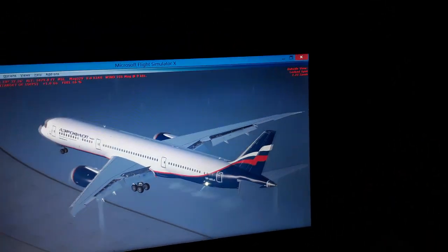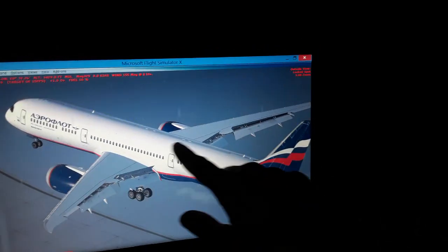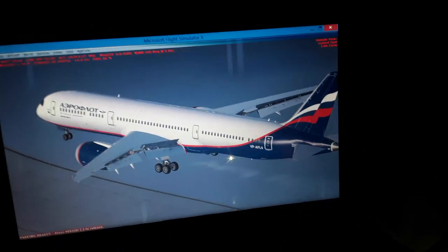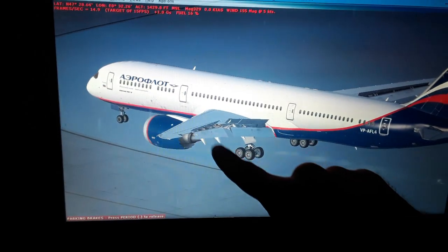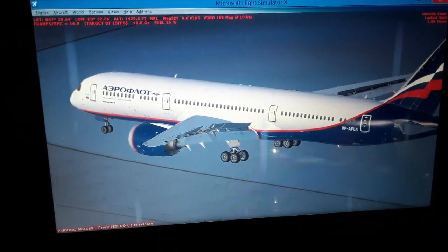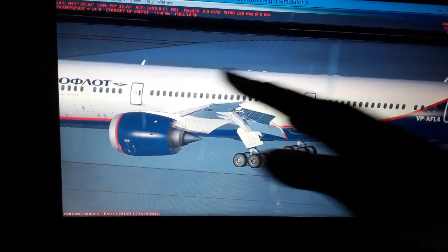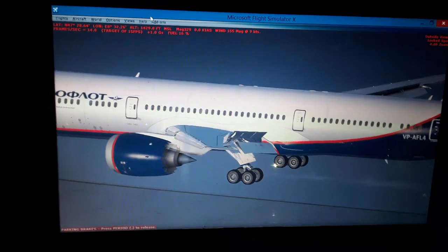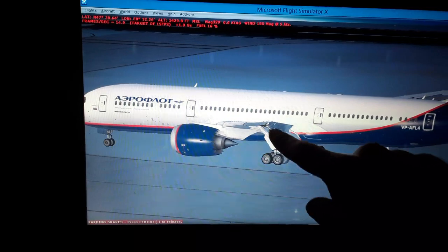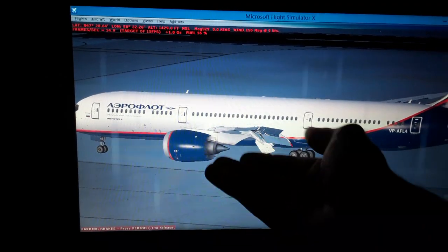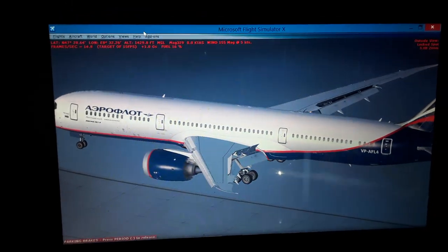So we have the center of gravity, the vertical axis pretty much here where the main aerodynamic chord is. Then you can see the bottom surface of the wings is more flat and has the curvature from the flaps extended, and as we're gonna be flying we're gonna have an angle like this. Using Bernoulli's theory of fluids, as we take off the airflow will be moving slower below the wings, so we're gonna have higher pressure, which pushes the wings and the weight of the aircraft up into the air.